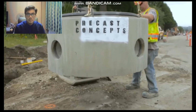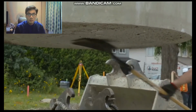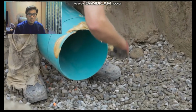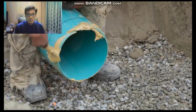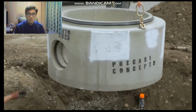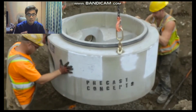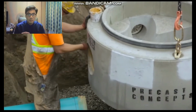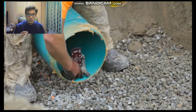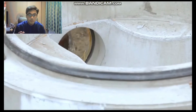For placing a precast concrete base into a trench, ensure that load-appropriate lifting clutches are used. Once raised, ensure no material is present on the bottom of the base. This allows for level placement as the base is lowered into position. Lubricate both the end of the downstream pipe as well as the outlet of the base that will connect with the downstream pipe. Lower the manhole base until it is the same height as the downstream pipeline.